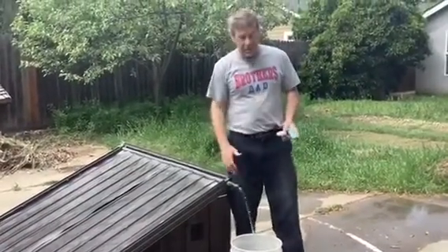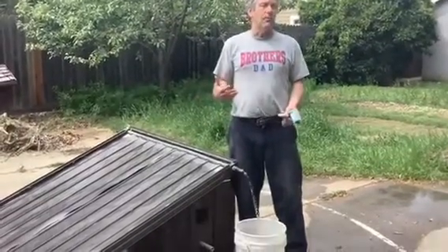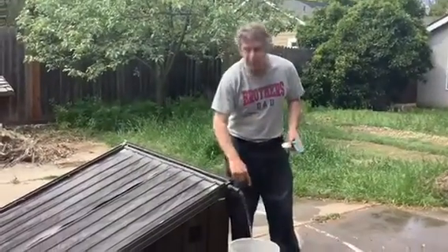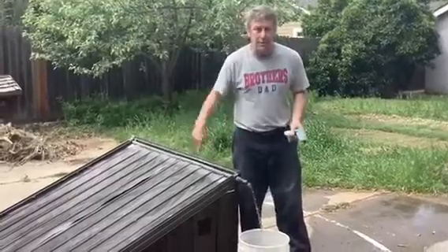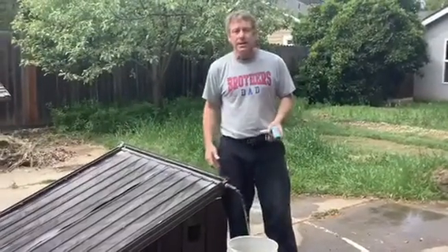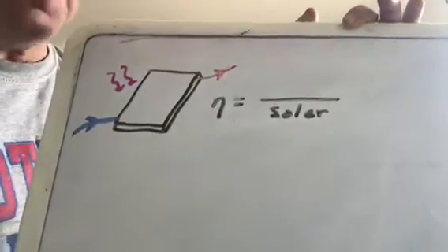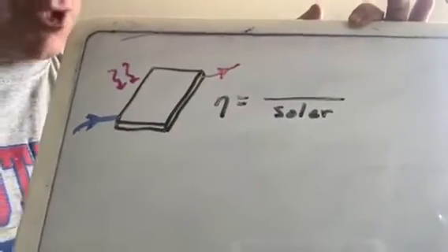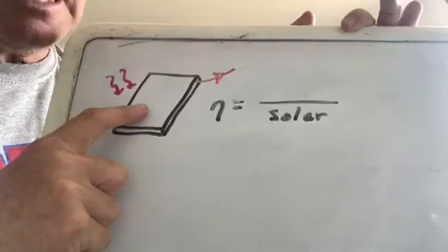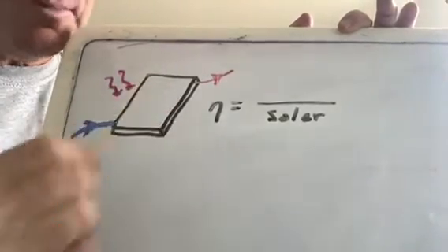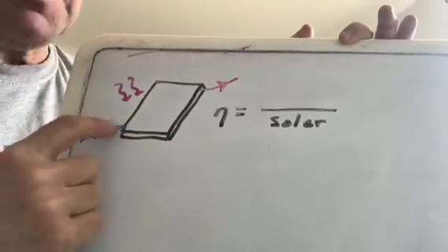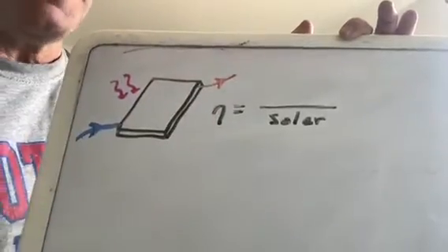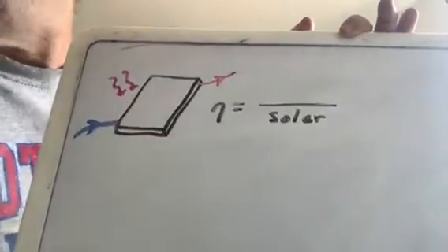Obviously, if it was a sunnier day, hopefully we'd be coming out about 90. And then really what we would do ideally, if we wanted to get really warm water, is have this water recirculate around as many times as necessary to get it up to the temperature that we want. So what we saw is just called the flat plate collector solution. Even though the collector plate has little ridges, basically it's pretty much flat. You have inlet water, you have outlet water, and the water comes out warm.